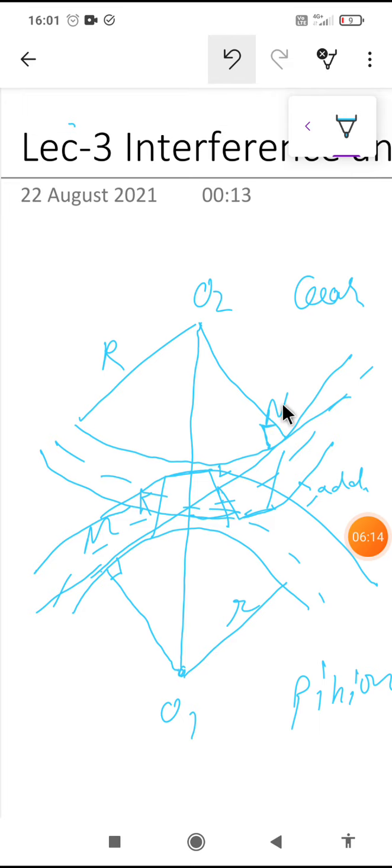It will be inside the base circle of the gear and not on the involute profiles of both tooth and wheel. The tip of the tooth on the pinion will then undercut the tooth on the wheel at the root. So this root will be cut by this tip, removing part of the involute profile of the tooth on the wheel, and this effect is known as interference.